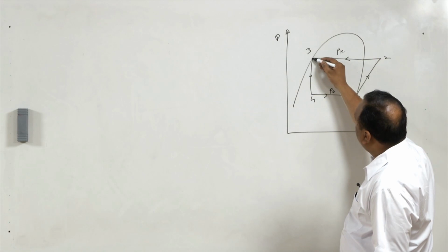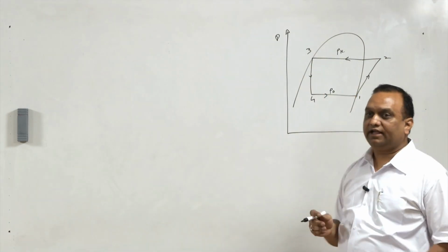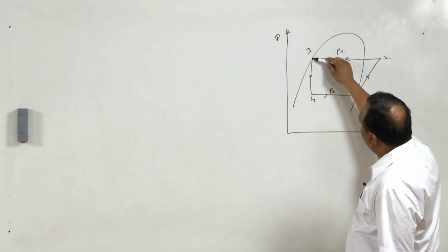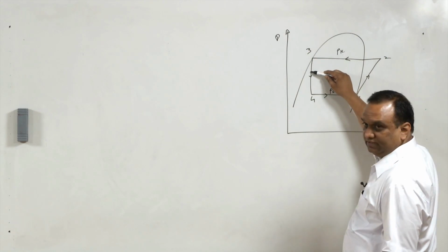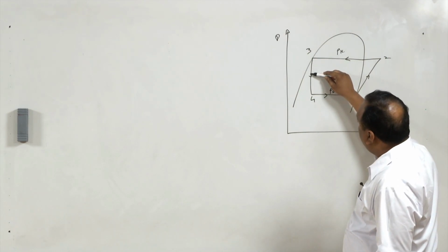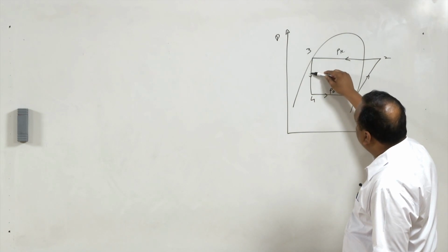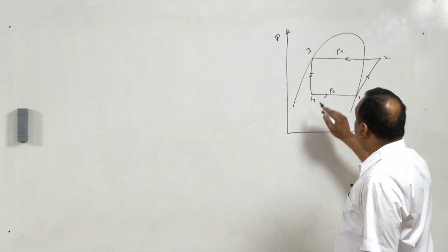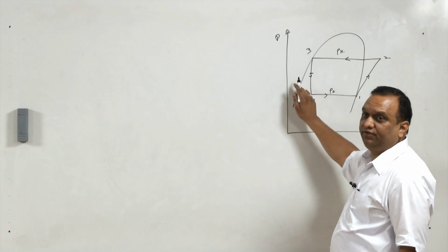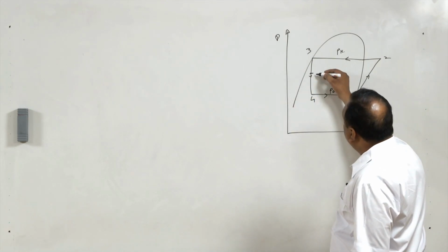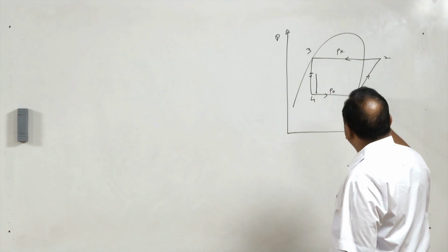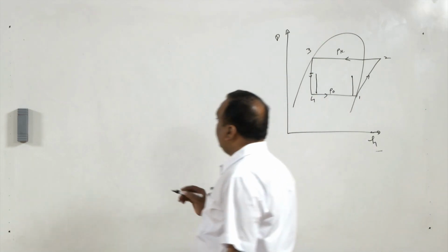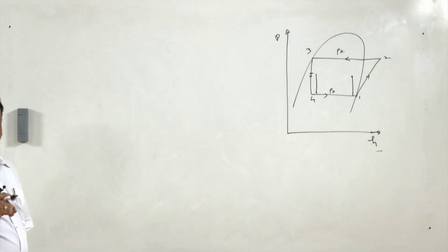Suppose it is a low capacity plant and capillary tubes are used as expansion devices. The refrigerant entering the capillary tube will be liquid, but slowly the flashing will take place. After expansion to a certain length, the amount of vapor becomes substantial, and the idea is to remove this vapor, because this vapor would get expanded and then be compressed again. So, in order to avoid this, a flash gas removal system is provided in the system.